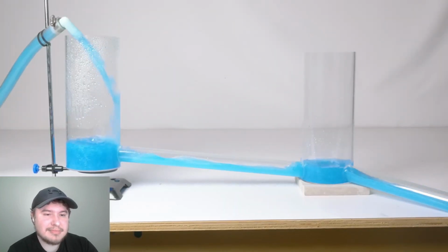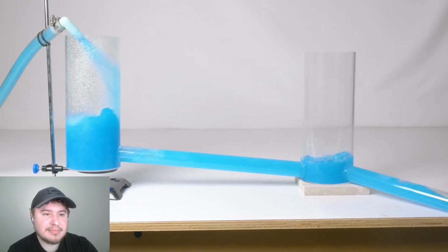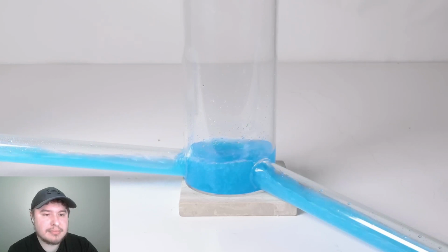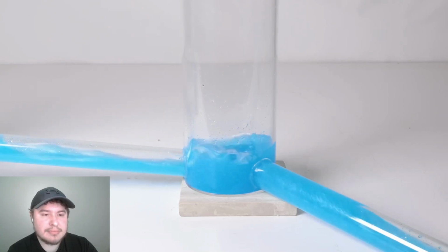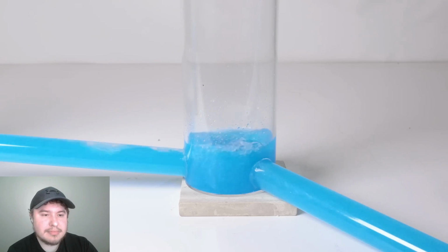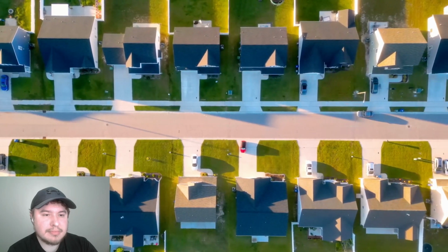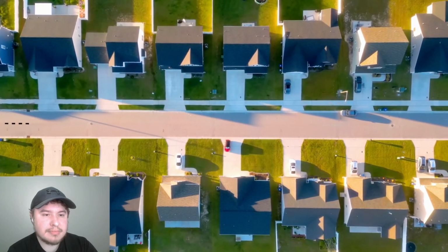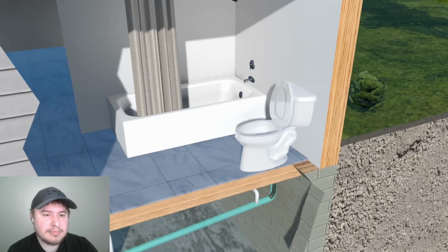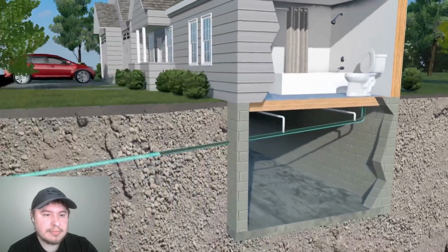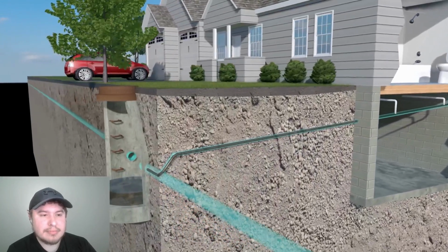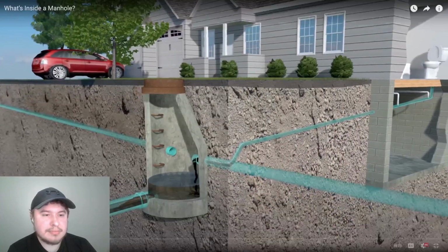Unlike regular plumbing where you use fittings to connect lengths of pipe together, sewer lines are connected with manholes. Any change in size, direction, alignment, or elevation is a place where debris can get caught or turbulence can affect the flow. So instead of elbows or T's in the pipe, we just put a manhole instead. In fact, unlike many underground utilities, you can usually trace the paths of a sewer network pretty easily because it's all straight lines between manholes. They provide a controlled environment where the flow can change direction, and more importantly, a place where technicians can get inside to inspect the lines, remove